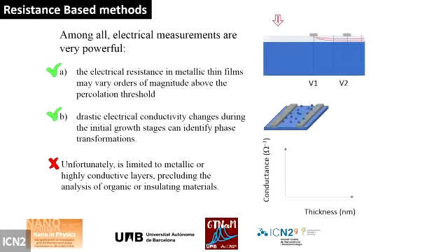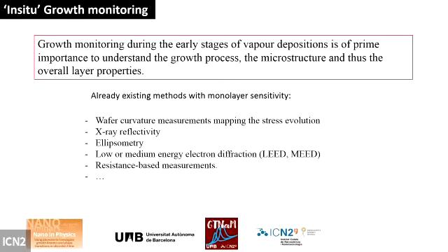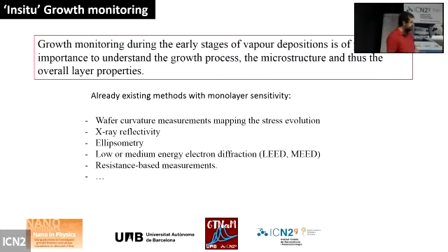There are many methodologies and measurement techniques to measure that information, and I'm mentioning a few of them here. The wafer curvature, the mapping of wafer curvature in order to monitor the stress evolution of the film, X-ray reflectivity, ellipsometry, low and medium energy electron diffraction, LEED and MEED, that are typically implemented in evaporator systems. And I would say that the most common and the most simple one is the resistance-based measurement.